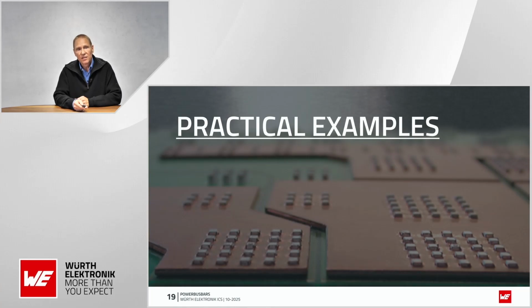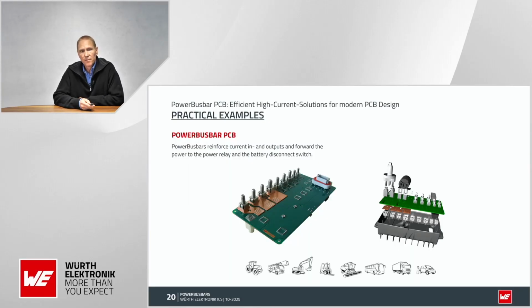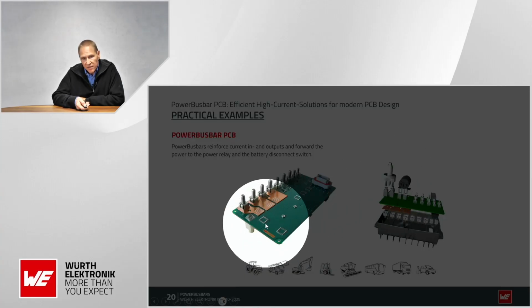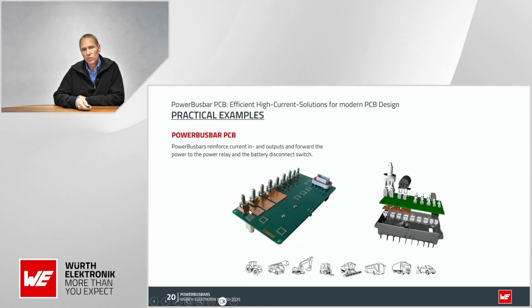Let us have a look at some practical examples. This shows a PCB that is used in a bus application, and here we use the bus bars for the input and output of a relay and a battery disconnect switch. What you can also see here in this application is that we use the press fit components from both sides.